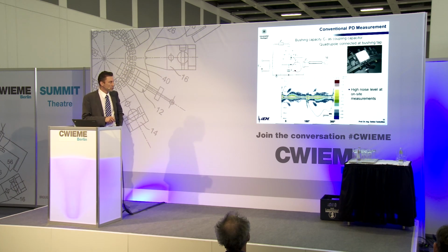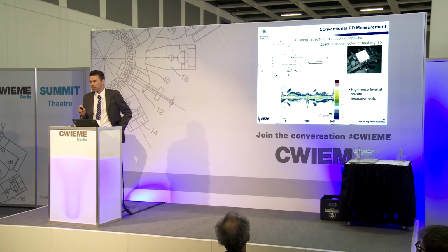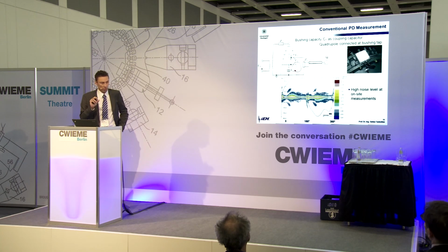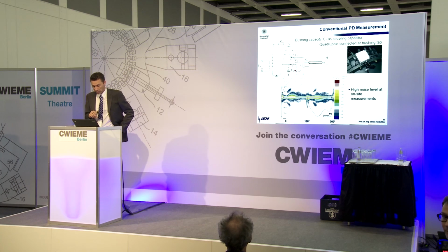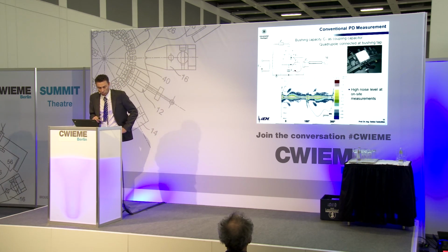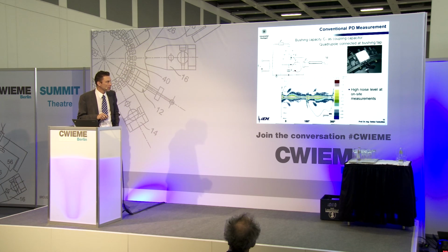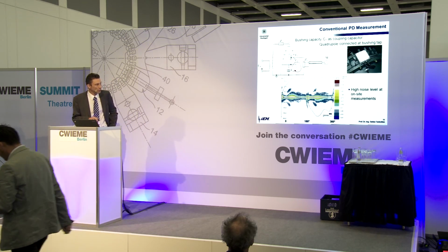So once you have partial discharges in the insulation system, a partial discharge is a partial flashover localized on one spot in the winding, so you do not have a big arc inside the transformer, but more or less little sparks. You can measure these sparks by connecting this measuring circuit, which consists of the bushing capacitance and a quadrupole. In order to connect the quadrupole, you need a measuring tap at the bushing. This is shown here in this picture.